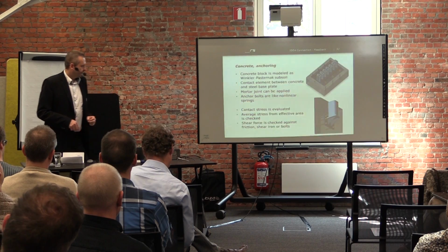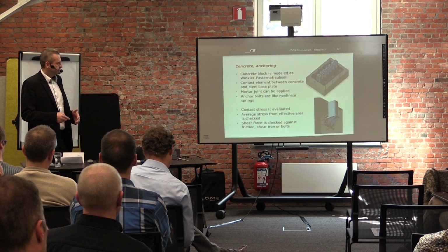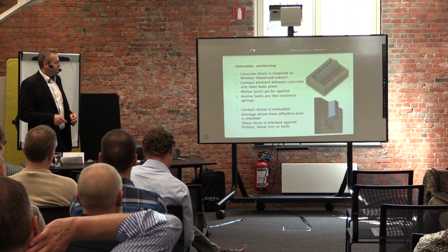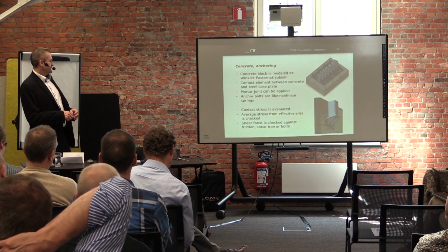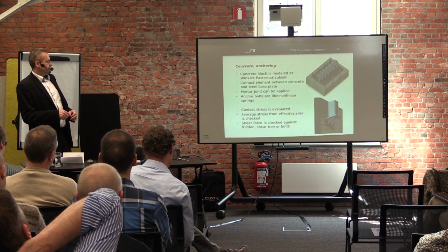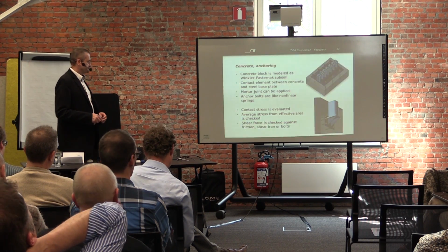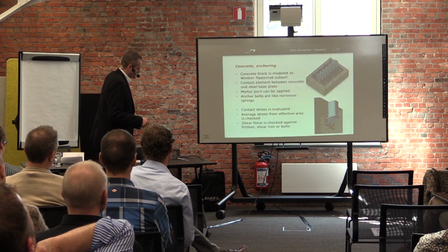Then we derive the effective area like in Eurocode, and calculate average stress on this effective area, and this is checked again against the concrete ultimate capacity.